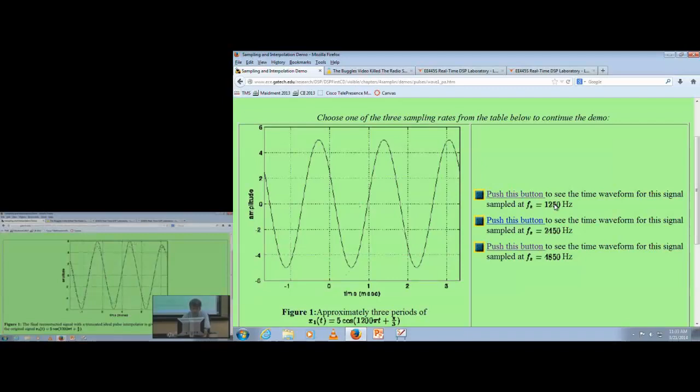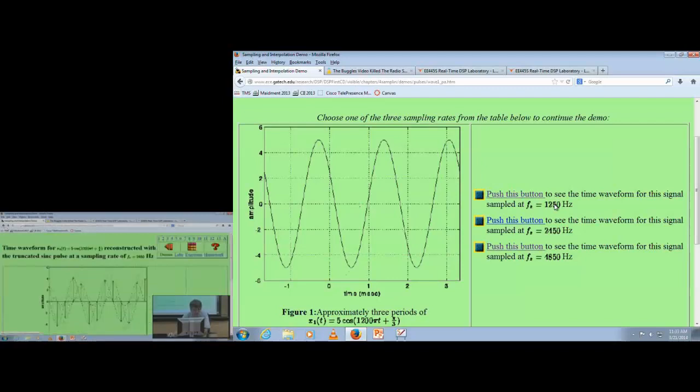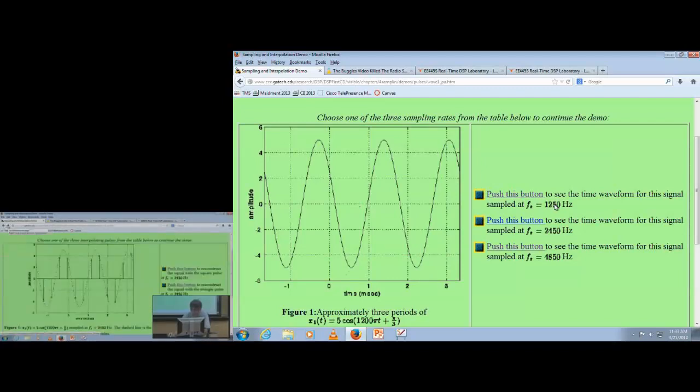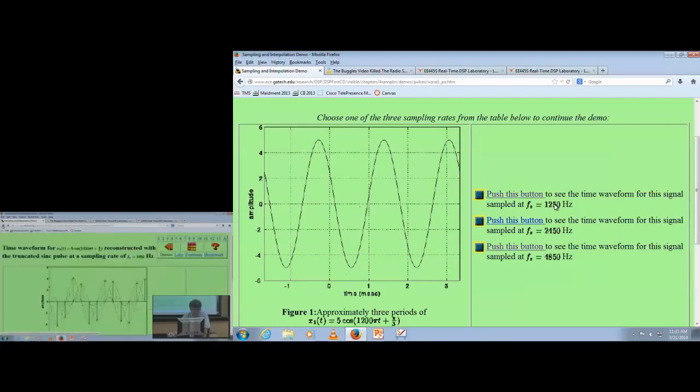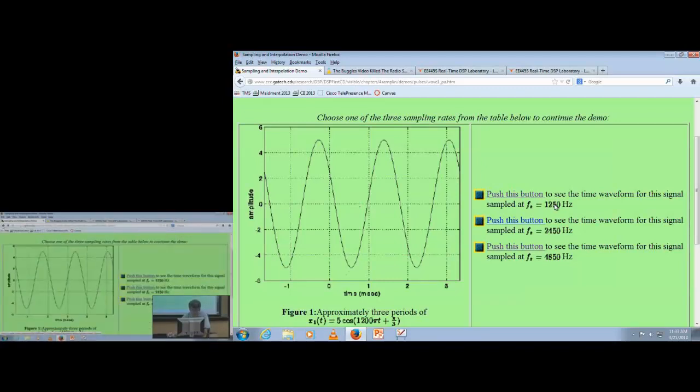But we're not getting quite high enough on the... I'm sorry, it's the other way around. It's going too high and too low. That's it. Right. So the reconstruction is a solid line. It's overshooting the valleys and the peaks. But not bad. So 2x makes it better. We're tracking the time domain waveform better. So let's do 4x oversampling.